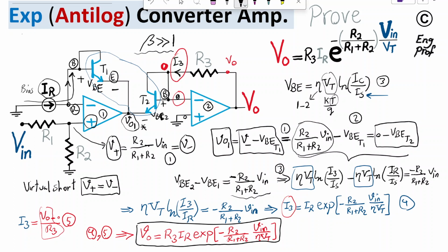R2, generally speaking, in this kind of simple circuit, R2 is selected to be considerably smaller than R1, so that we manage the amount of additional voltage we are adding to VBE, because VBE of transistor has a limited wiggle room. So I hope that this example is helpful.